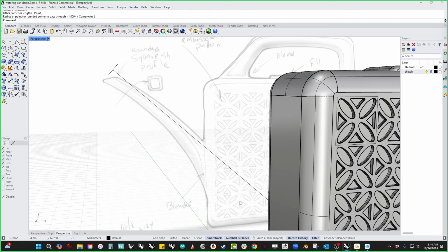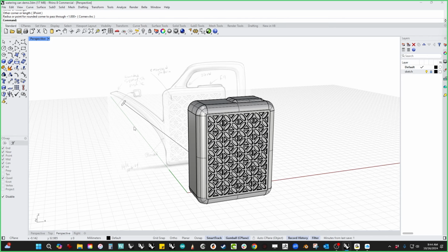Now, that around curve is super useful because what it does is it puts it perpendicular to the curve, however it sits out. And the reason I'm doing this off of a straight line is because I want the simplest version of this surface to start with. This curve only has 2 points, which means this is going to be a degree 1 surface going in this direction, which is what I want. And then we're going to mess with it.